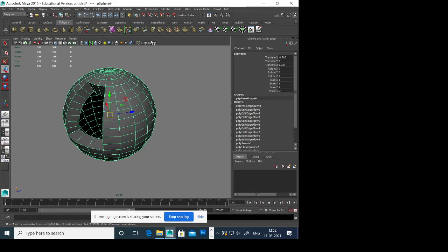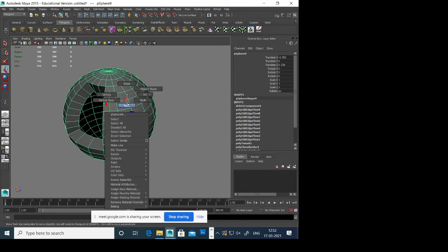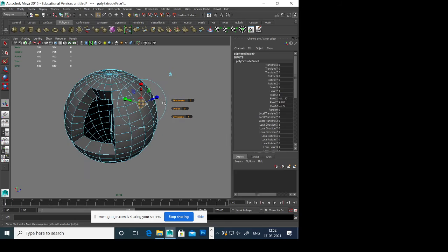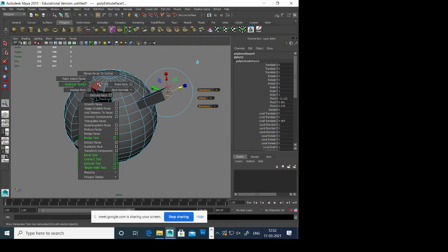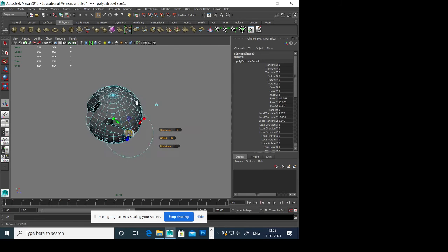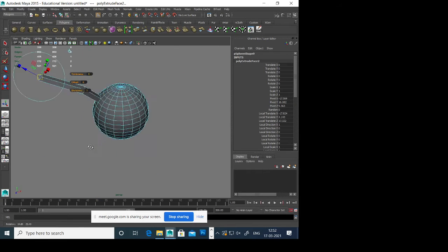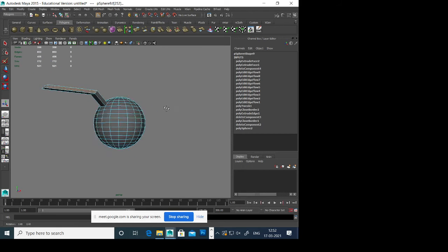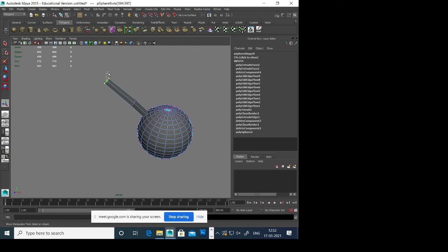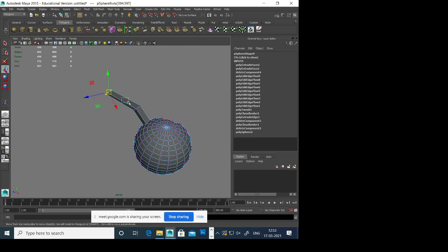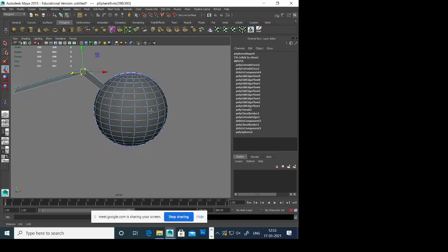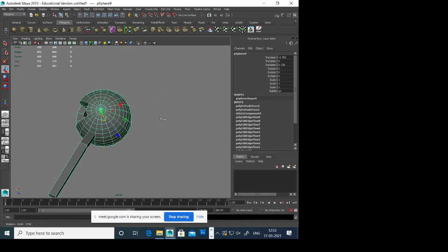After creating this, you can see the basic options, extrude. Suppose you want to extrude something, click on this option, extrude. Same thing, you have shortcuts also. Whatever you want to create, you can do it really fast and modify things. Suppose you have all this cut and these options, same thing, merge vertex, create triangle, split it, same thing.